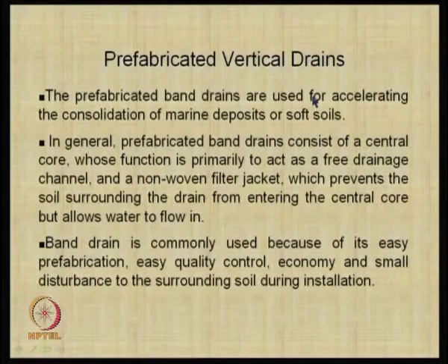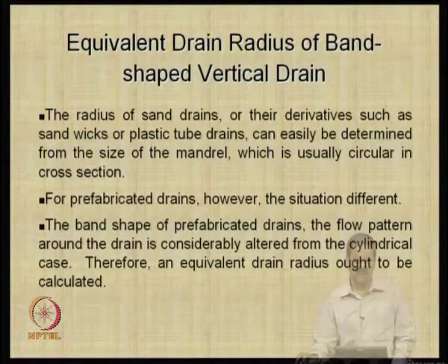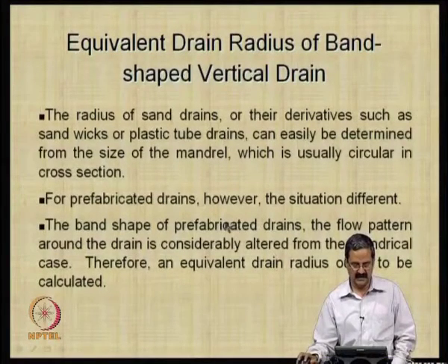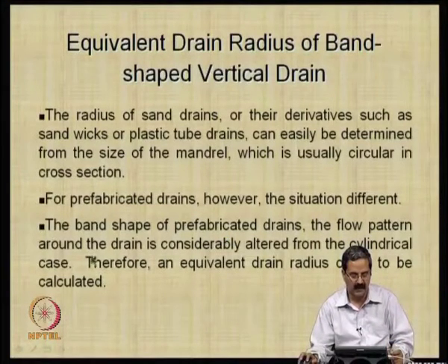And as I just mentioned, PVDs are much more comfortable to use because of the ease of fabrication, quality control, economy, and sample disturbance to soil is very less during installation. This is another important point that one should realize. The difference is that we had an equivalent diameter there, and now since the shape of the drain is more of a rectangle, the flow pattern around the drain is considerably altered from the cylindrical case.